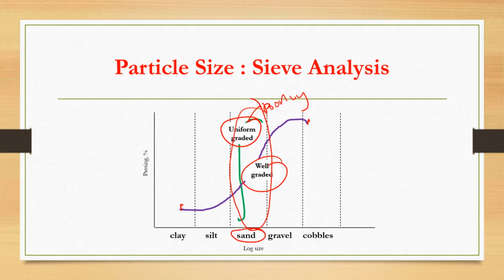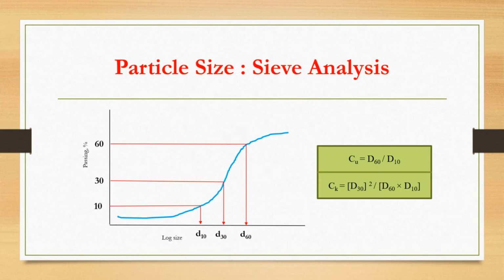So from that curve on your particle size distribution diagram, you can easily identify. Additionally, results of grading tests can also be tabulated using geometric properties of the grading curve. These properties are called grading characteristics. First of all, 3 points are located on the grading curve, namely D10, D30 and D60.